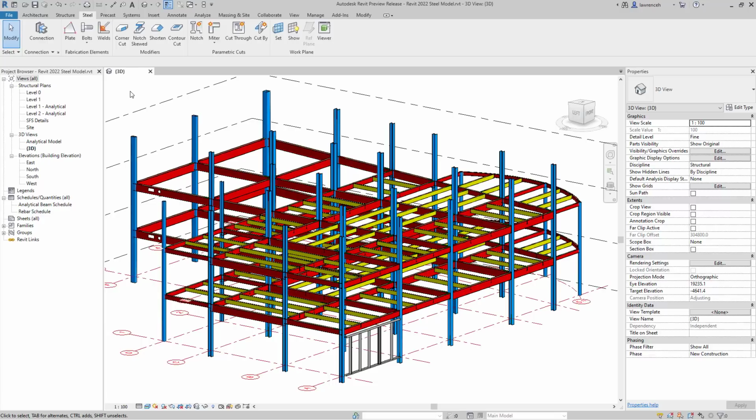This feature essentially allows you to create a library of standardized steel connections that can be placed automatically based on a number of different parameters such as geometry, the section shape, materials, and member end forces. The standardization of connections, particularly simple connections as found in multi-story braced frames, is an essential process for the control of costs. The cost of steel connections can be greatly reduced if they are based on standard details, which in turn reduces fabrication and detailing costs.